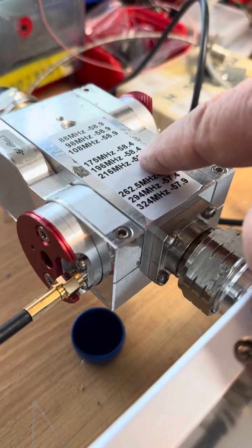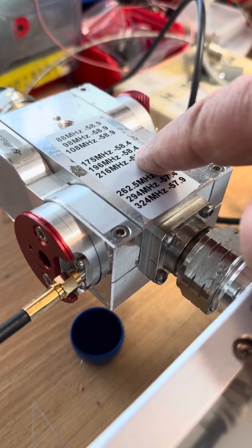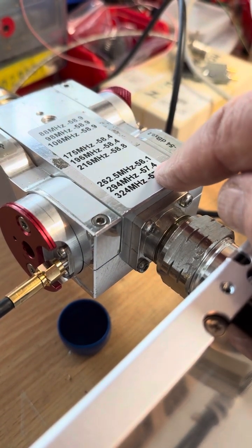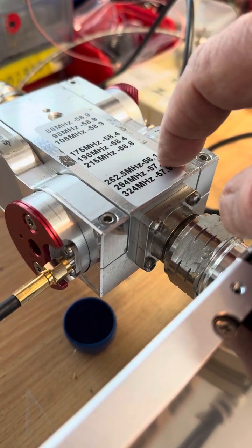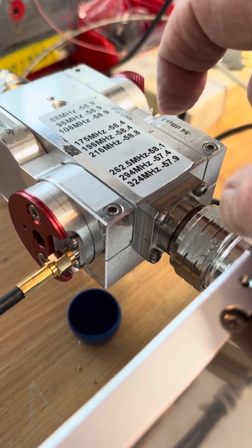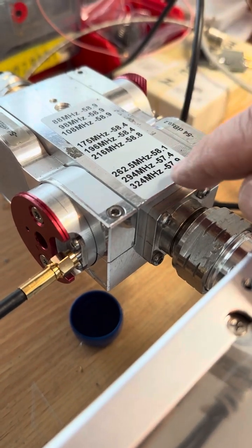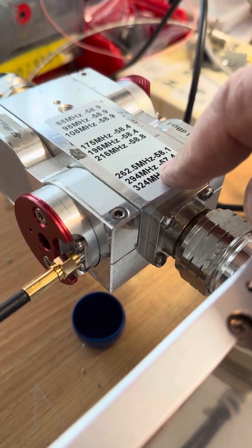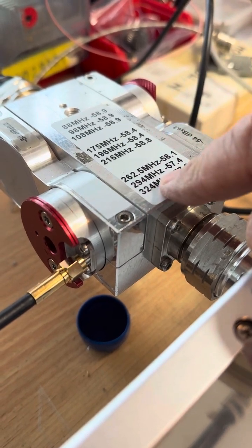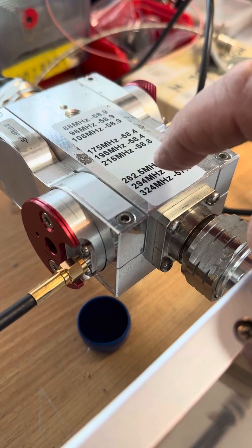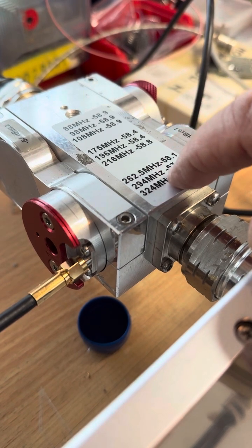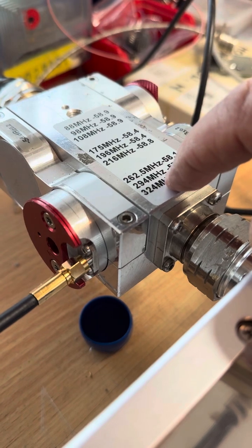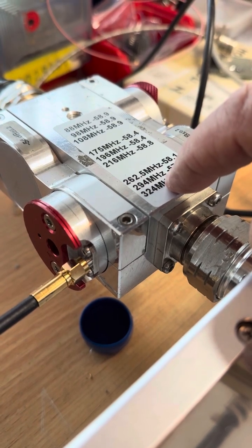In the second harmonic, also minus 58 dB. In the third, minus 57. So we have only 1 dB of difference, and that is the worst case, an emphasis of 1 dB at the second and third harmonics. So the measurement shown is not worse than the real measurement.